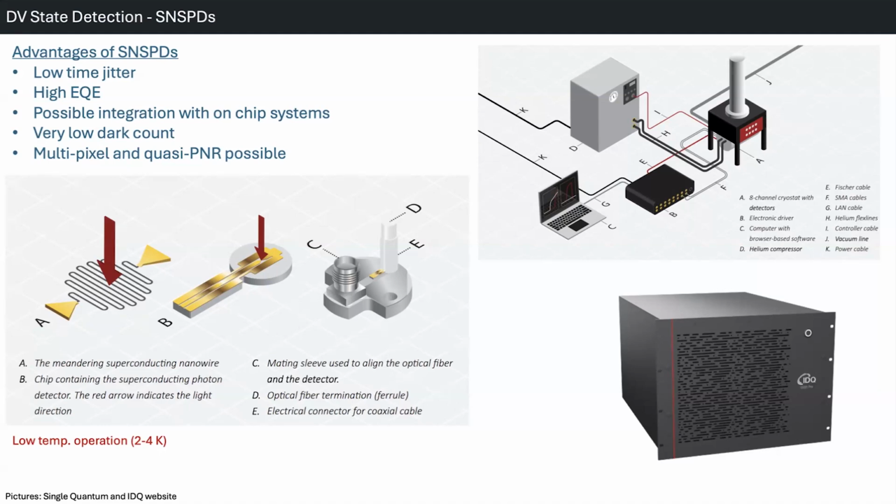Since they usually use single mode fibers, if you remember from your electromagnetic theory lessons, in the last fifth chapter of Jackson's book, when you solve the equations, you will see a cutoff region for single mode fibers. So you cannot use all the visible or infrared range. It will be a few hundred nanometers range, like 150 nanometers. The working range depends on your optical fiber.